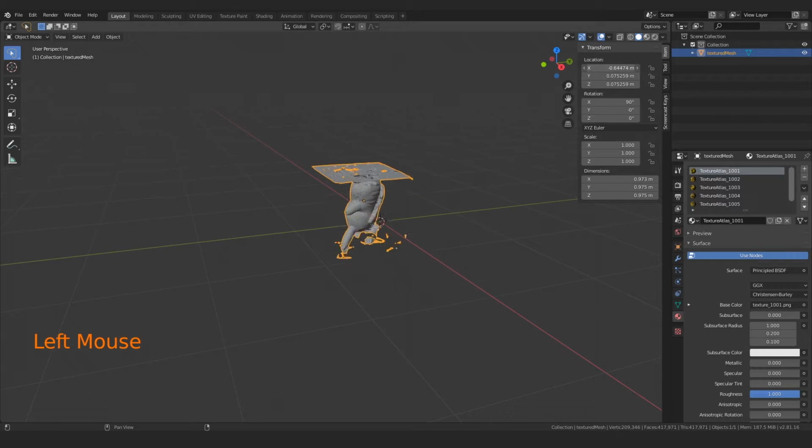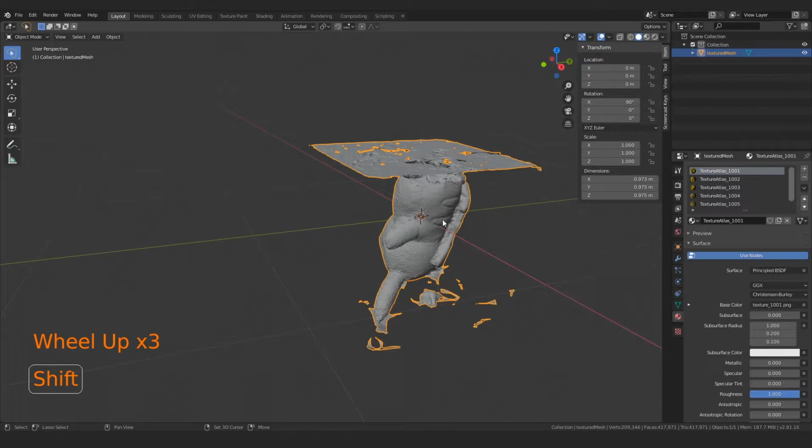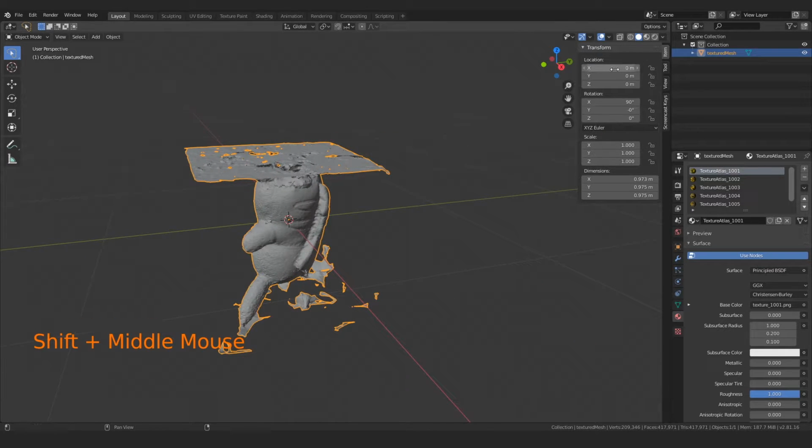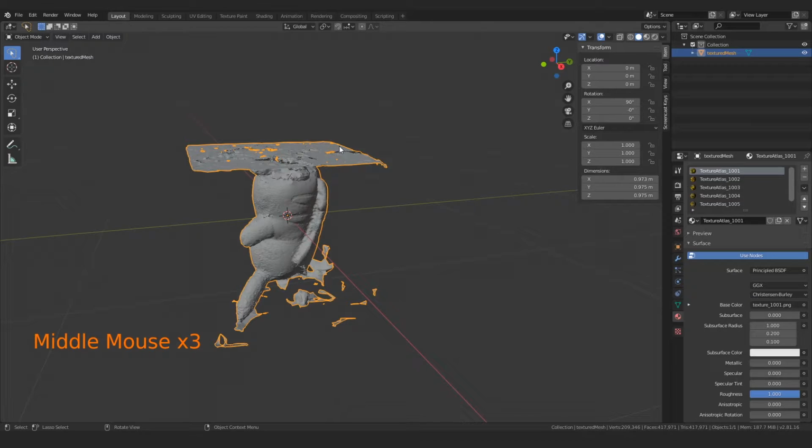Really quickly there, you saw me dragging there, but I'll click and drag down these 3 options, which will allow me to input the value of 0 and press enter, and you'll see that my Pikachu now jumps to the center of the world, which is at coordinate x0, y0, and z0. So those are those axes values that I was talking about before.